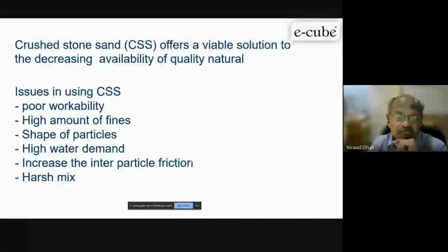If you see in reality, it gives resistance while moving in the concrete itself, and you will find it is not very good concrete. The concrete becomes harsh with no cohesion. So your aggregates will go away from the paste. That is not good concrete for a quality structure.